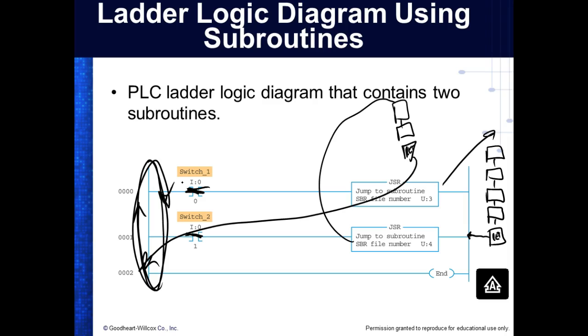So that would be very confusing if I could bring my subroutine back from a different spot than I came from. So JSRs will always do what? Well, that's not true. Once you find the address, once you know where the stack's at, you can change the return address. But that's the only way you can do it, is change the contents of the stack. And right now, we don't have control of the stack, right? But we can't specify where it goes back to. What it's going to do is pull all that information off the stack. So no, the return does not have to specify, that's a good question. Any more?